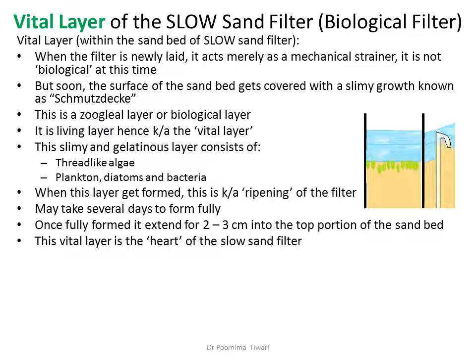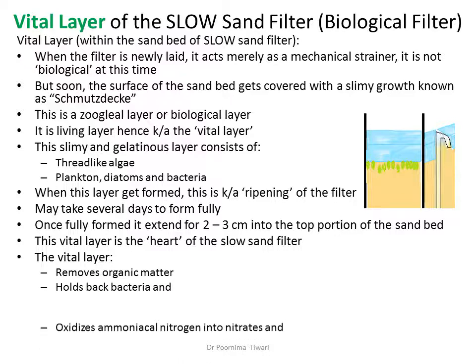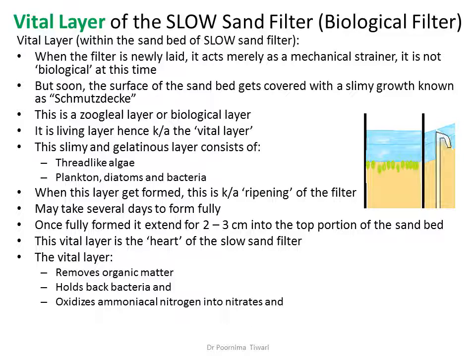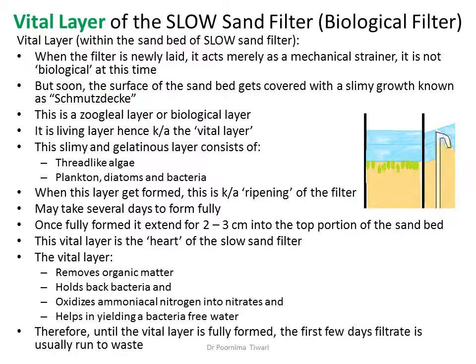This vital layer is the heart of the slow sand filter. The vital layer removes organic matter, it adsorbs it, that is, holds back bacteria, and oxidizes ammoniacal nitrogen into nitrates and therefore helps in yielding bacteria-free water. Therefore, until the vital layer is fully formed, the first few days' filtrate is usually run to waste.